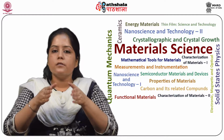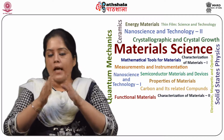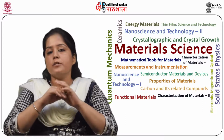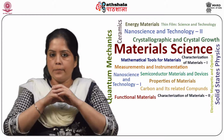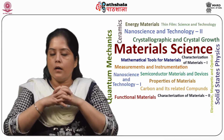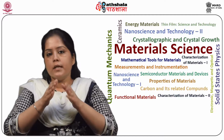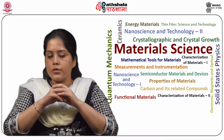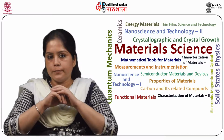The advantage of this method is that it can be used to determine the full Q matrix of a ferroelectric material. And the issue with this method is that the piezoelectricity developed in the material under study should originate only through electrostriction.